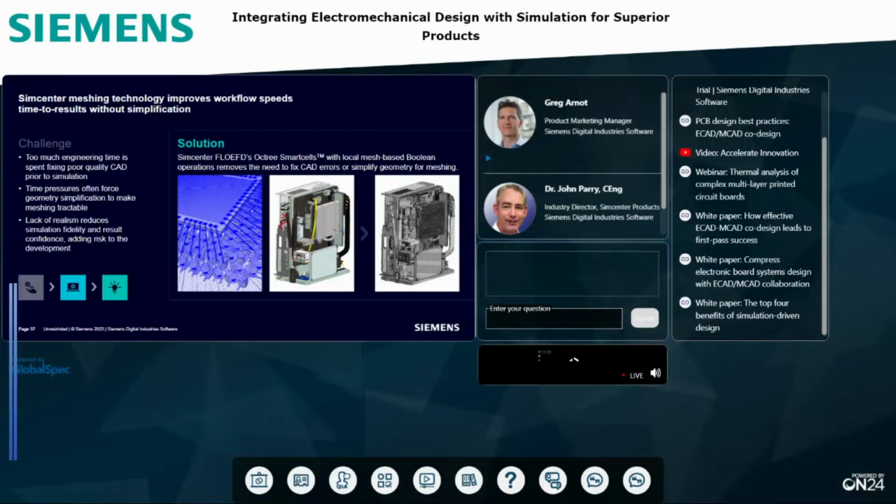So complexity has been noted as a growing challenge in the accurate simulation of electronics products, boards and systems. Our smart cells technology uses the intersection of an octree-based grid with the geometry in order to create the computational mesh. The accuracy is controlled through local mesh refinement on the unsimplified geometry. This technology completely eliminates the need to simplify the geometry for simulation.